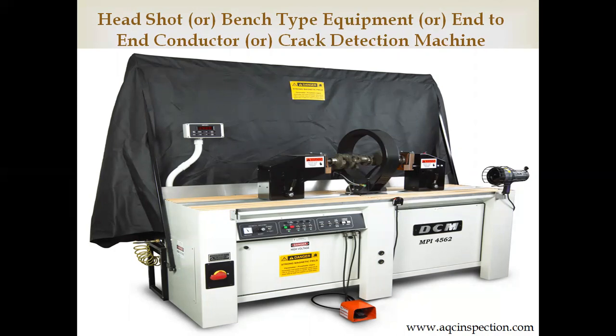So here both longitudinal and circular magnetic fields can be applied. When current is applied from this copper conductor to the other copper conductor, a circular magnetic field is induced in the material. When the current is applied to the rigid coil, a longitudinal magnetic field is induced in the material.